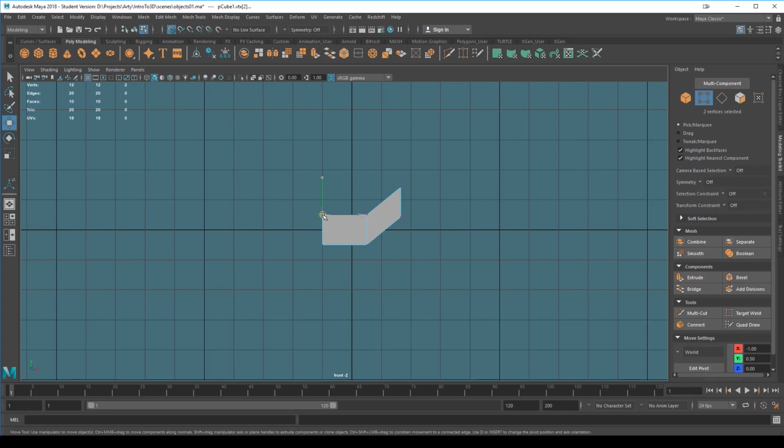If I just have those verts selected, it'll snap exactly to the grid cross section. If I have them all selected, you can see it's going into the center. And the reason it's doing that is because it's averaging, it's finding the middle distance between these, and that's where my pivot is, and it's snapping that pivot point. So that's actually what I want. So I'm just going to snap this one here, this one like this, and let's see, I'll just move these out. I think that's a good shape, so we'll go 1, 2 up, and then 1, 2 down.